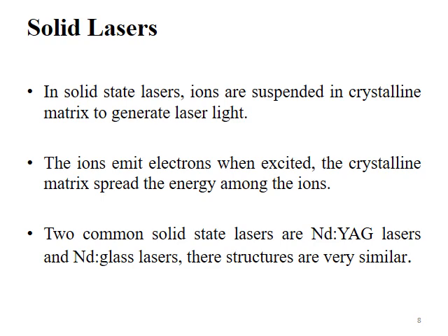The Nd:glass laser's glass rod has the advantage of growing into larger size than YAG crystal, but the lower thermal conductivity of glass limits the pulse repetition rate of the Nd:glass laser.